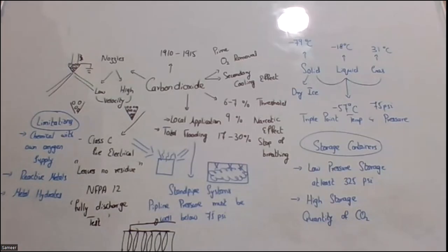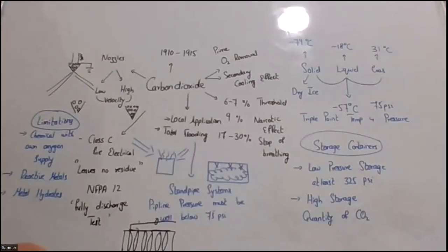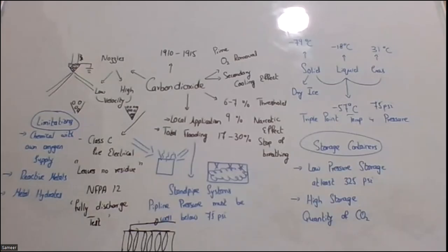Okay, so this is all for the carbon dioxide systems. All operating devices in the maintenance, okay, all operating devices should be tested annually. Usually we do the quarterly inspection of the carbon dioxide systems and the portable extinguishers. Quarterly, like after every 3 months, we check the portable carbon dioxide extinguishers. Standpipe systems, depending upon the occupancy's requirements, can be semi-annually or annually, but semi-annually or annually also depends upon the installation requirements that have already been completed within a facility.